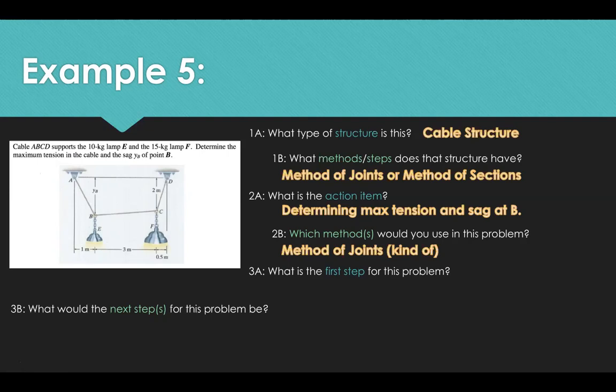One of you quiet people. Free body diagrams and then taking method of joints at whichever one you want to do. So yes, but what do you have to do before you separate it into a method of joints problem? Call for external forces. Exactly. Which are the reaction forces in this problem.